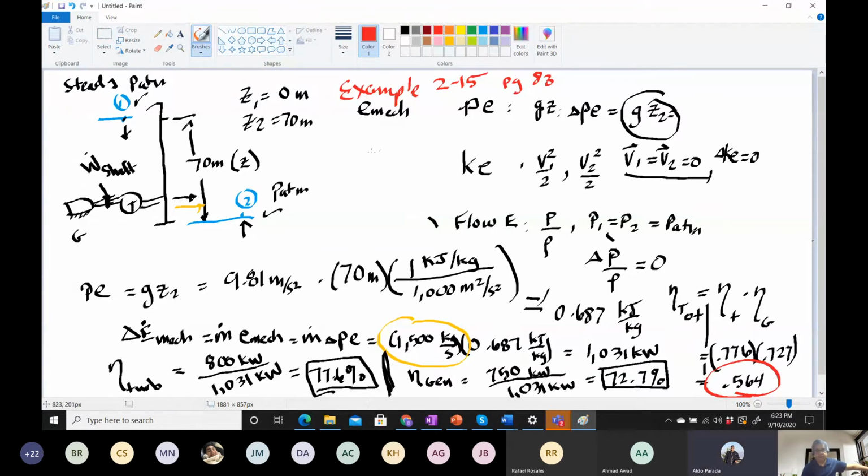All right. Professor, I have two questions really quick. So the flow energy is 0 because it's open to the atmosphere, right? So technically there's no flow energy. Yeah, because it's open to the atmosphere. We decided that we're only considering points 1 and 2 here. We have to pick two states, and those are the two states.